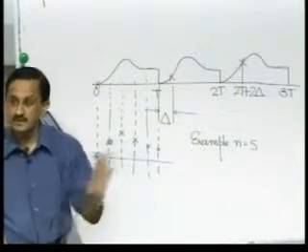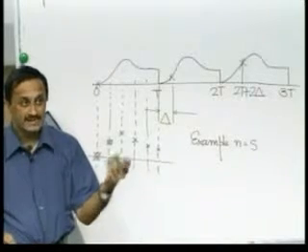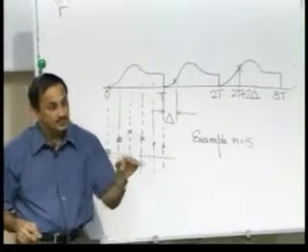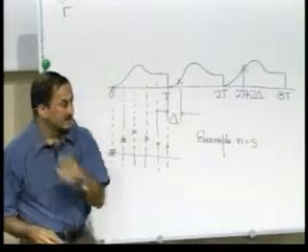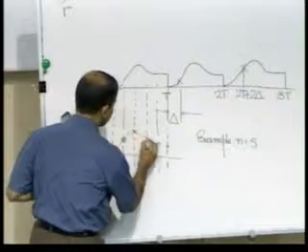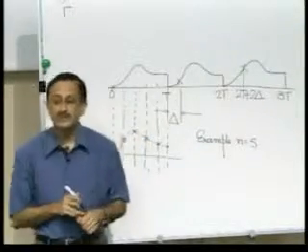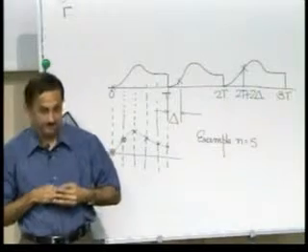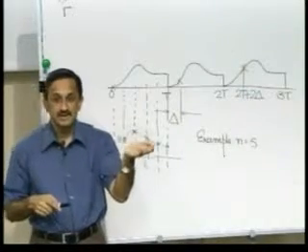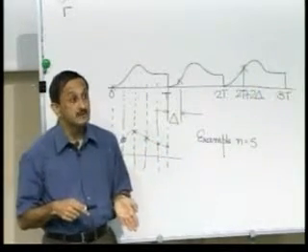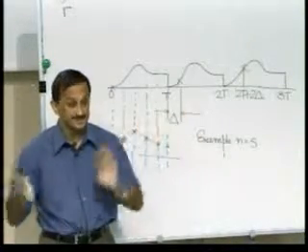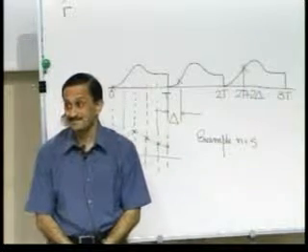How we do it, we shall not bother at the moment, but one can visualize it's some kind of a low pass operation or some kind of a smoothing operation, right, would give us a smooth waveform joining these points, which would closely resemble one period of the original waveform. So, now instead of trying to sample at the Nyquist rate, I have actually brought the sampling rate down, so that I take n samples over n plus 1 periods, less than one sample in a period.